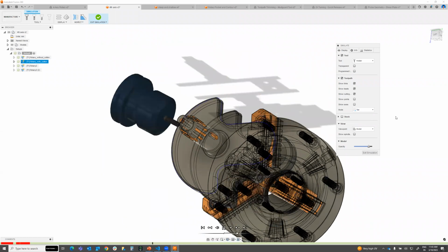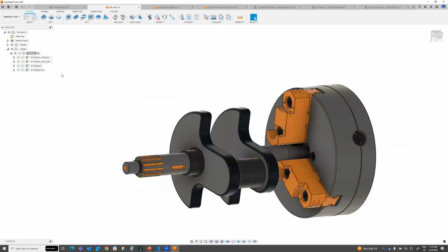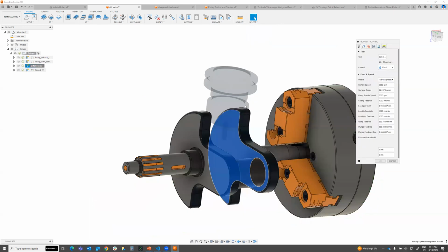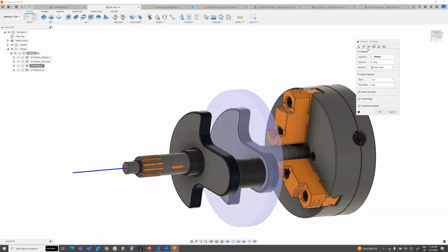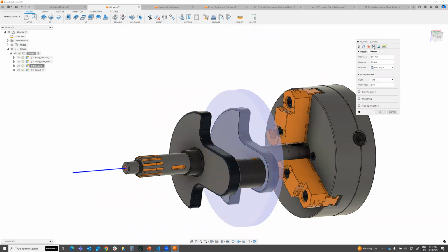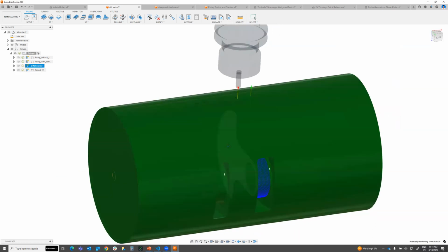Okay, apart from this automated tool overhang, now I will go into a different strategy. I want to do the steep and shallow option for inside of circular or spiral. I will go for the linear option, like I want to do the toolpath for the straight. Okay, this is the rotary, and here there is an option called line. Just I will select inside of the spiral or the circular, I will use the line. Now you can see my toolpath was calculated with parallel lines.